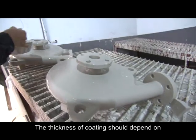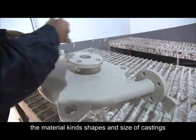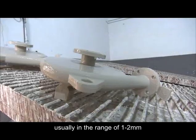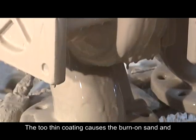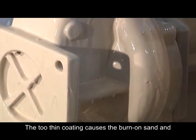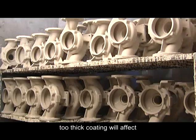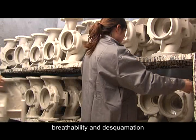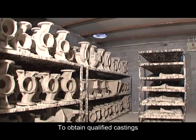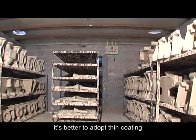The thickness of a coating should depend on the material, kind, shapes and size of castings, usually in the range of 1 to 2 mm. Too thin a coating causes burn-on sand and decreases the protective effect. Too thick a coating will affect breathability and cause deformation. To obtain qualified castings, it's better to adopt a thin coating.